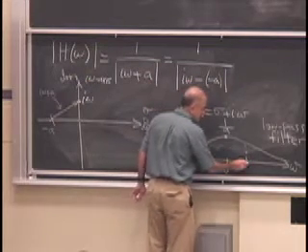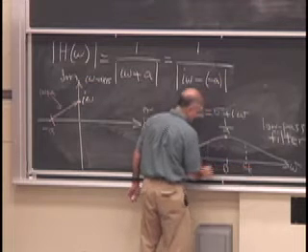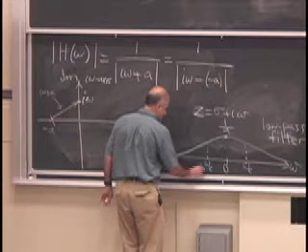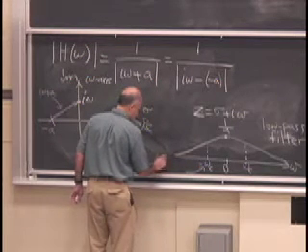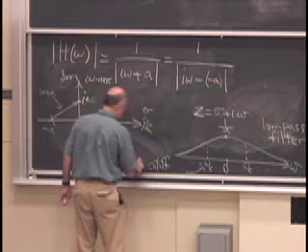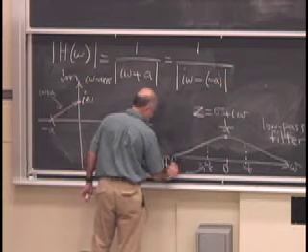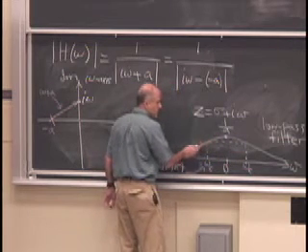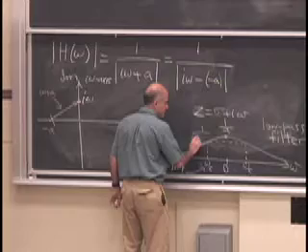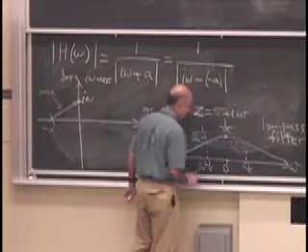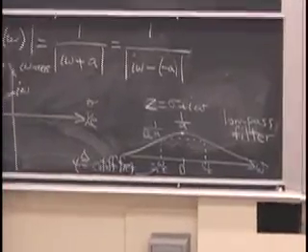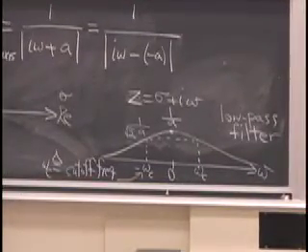It's the frequency, and they call that the cutoff frequency. Omega C is the cutoff frequency. It's the location where you are 1 over square root of 2 times the peak. Can't remember how many dBs that works out to, 6 or 3, one of those. If you have a scientific calculator, can you please figure it out? It's what? 3 dB.